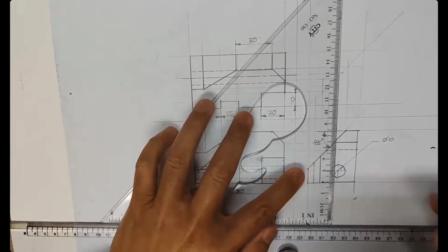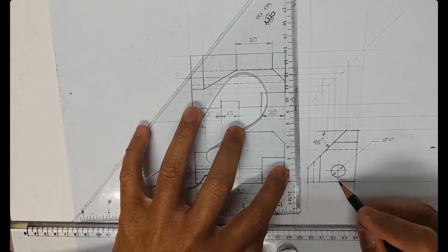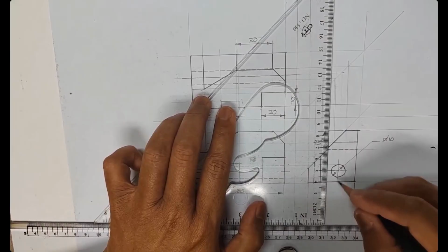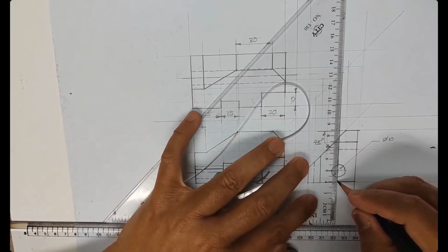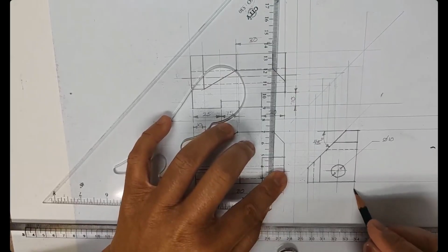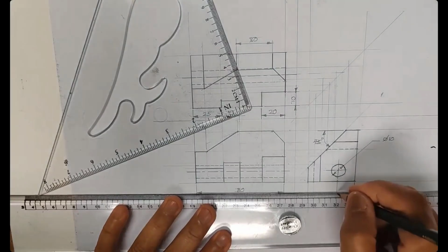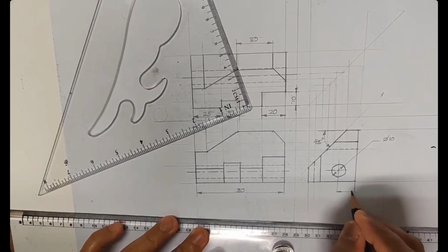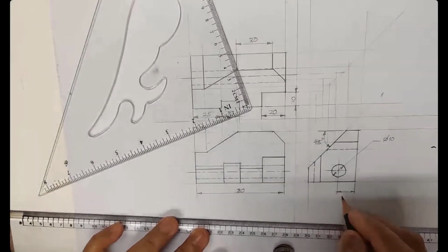Okay, the position of the hole should be put on the third view because it's clear. I have a center line, center mark of the circle. My extension line of my dimension has a gap, not passing to the object line, a little bit, 1 millimeter from that center mark. So I make the extension line pass through the object and go down like this. My extension line also does not touch this corner, it has a gap. So I make a dimension line here to position the horizontal dimension of the hole. Okay, clear guys, I need to be clear. This one also has an extension with a little bit, 1 millimeter gap. So here is the position,